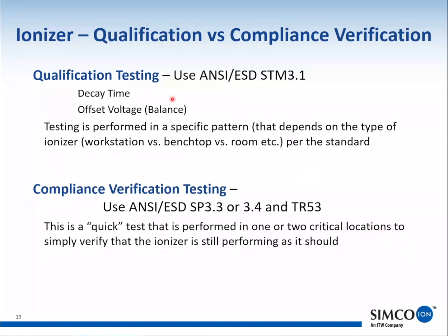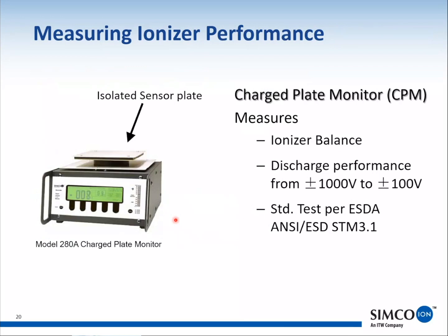Again, the difference is that qualification testing is something that, say, Tim will do, or he'll evaluate a laboratory's test done with this to pick this ionizer vendor over this ionizer vendor, or this particular ionizer type over this one, and he puts them on an AVL. You buy them, put them in your work areas, but you want to be able to do this compliance verification testing to make sure that they're working properly after you've installed them and on an ongoing basis. So those are the different types of tests you'll hear about.